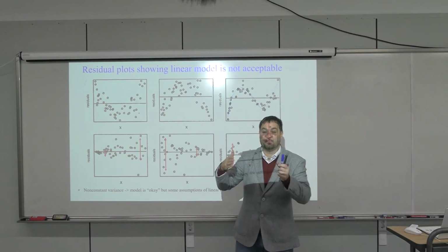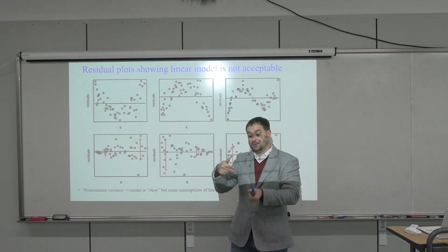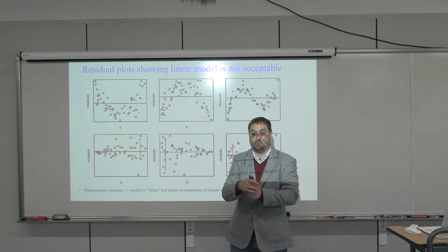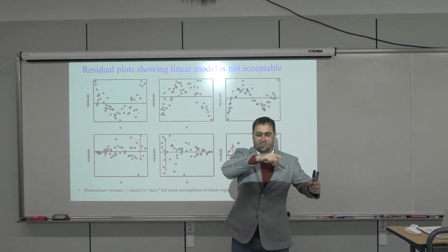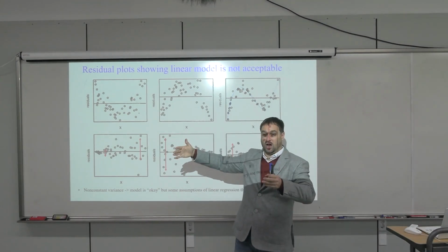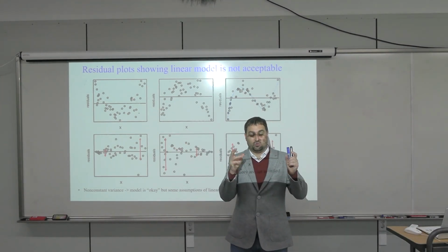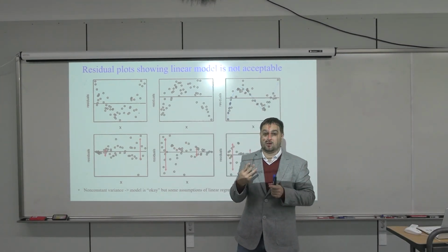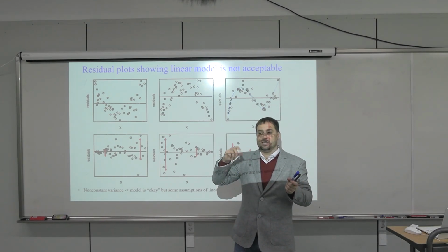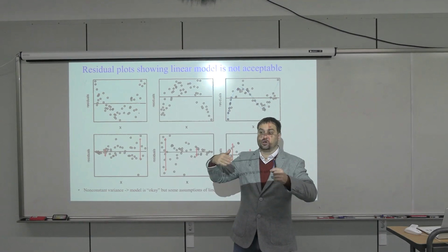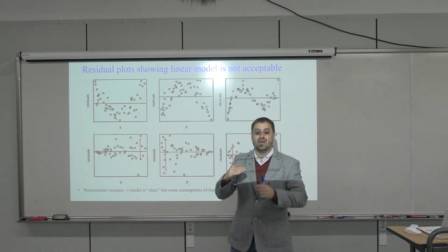Then we're using maybe a bathroom scale for the medium weight objects. And then we're using one of those giant scales, like when they have the big truck, where they weigh the whole truck. So in your experiment, you're using three different measuring devices. You have to calibrate each one of those scales, and usually you're trying to calibrate it to a 0.